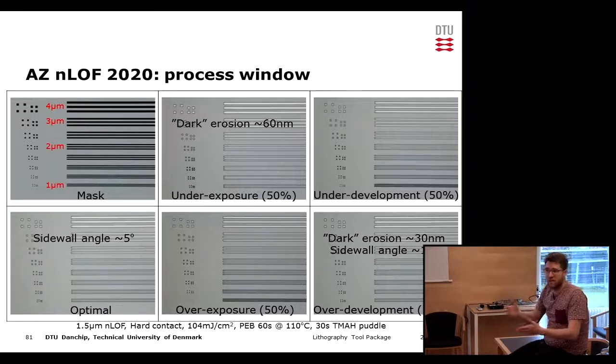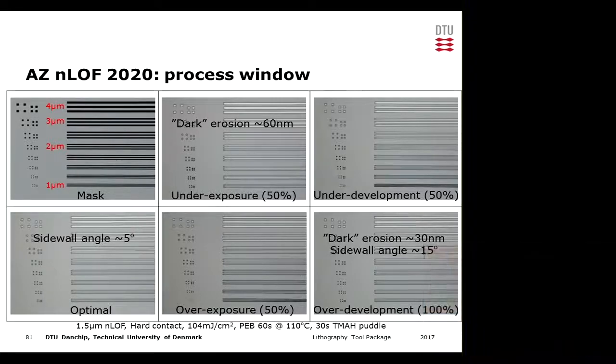But yeah, so there's some things you can do there. Another thing to keep in mind is that if you are doing lift-off, and the lift-off process is a little bit problematic, it takes a long time, or some of the structures don't want to lift properly, then you can also use this. You can do the overdevelopment to get a nice negative sidewall angle, and you can also keep in mind that if the dose is low, then the resist is easily dissolved by the solvent.